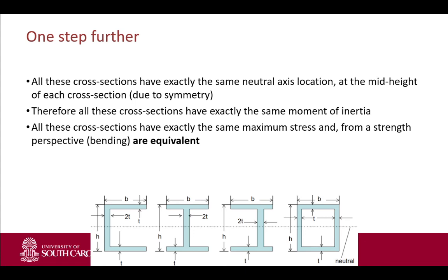If your applied moment is the same, your moment of inertia is the same, and based on the dimensions your maximum y is also the same. So it doesn't matter if you have a C section, an I, a different C, or a closed section, all the maximum stresses will be the same. So what we had in torsion, that we want to stay as far away from an open section as possible, is not necessarily true for other problems like a bending case.